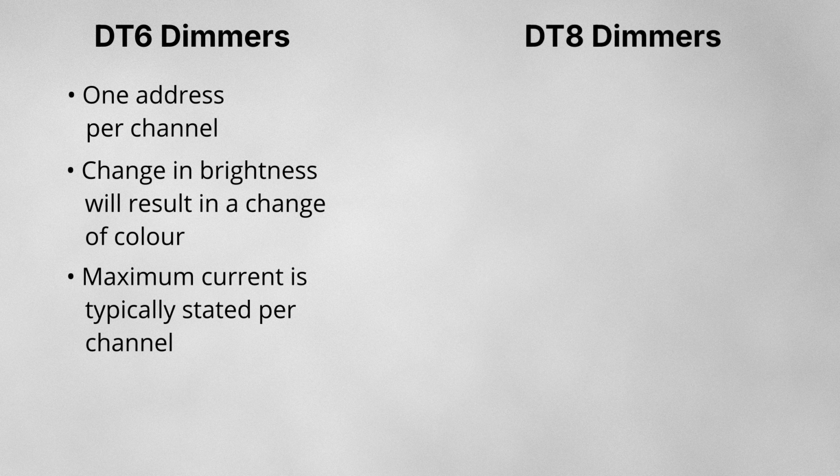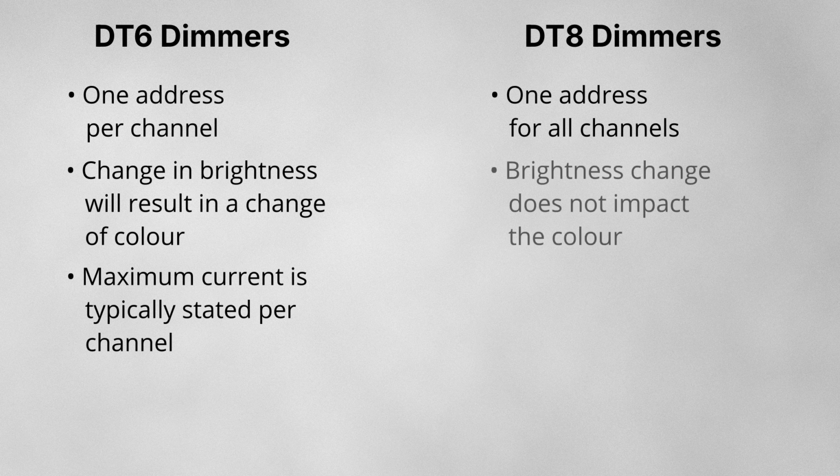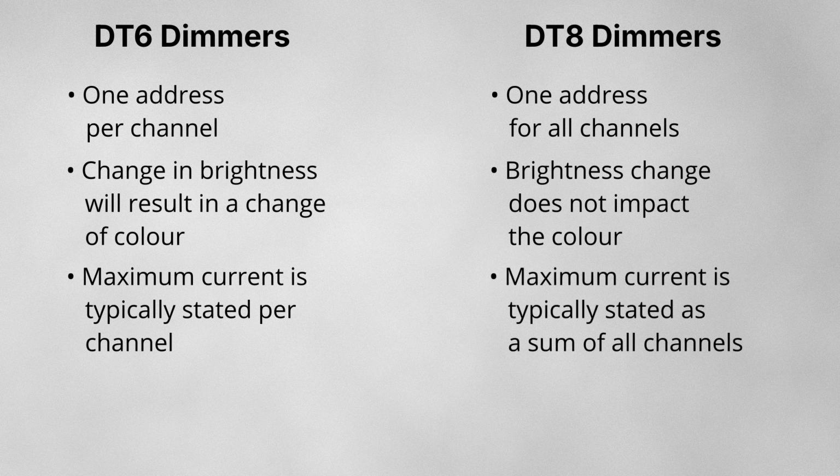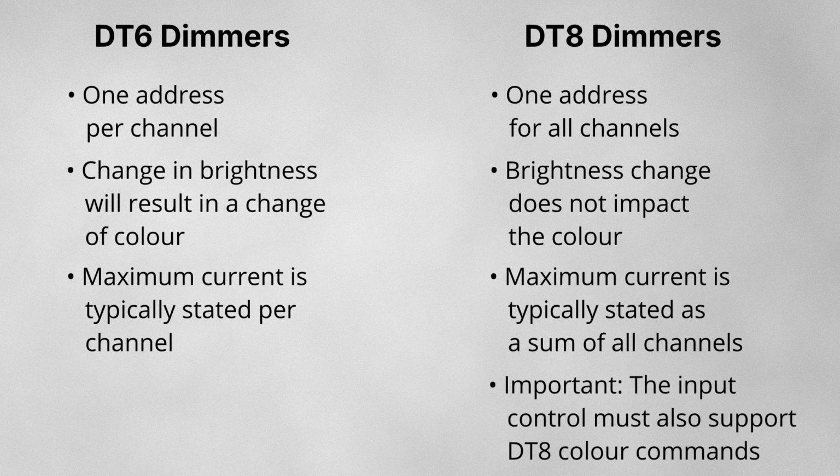With DT8 dimmers, one DALI address is assigned for all channels. All channels are controlled together in brightness and color. Maximum output current of the dimmer is typically stated as the sum over all channels. Important: the DALI control device used needs to support sending DALI DT8 color commands. All Lunatone control devices support DT8 commands.